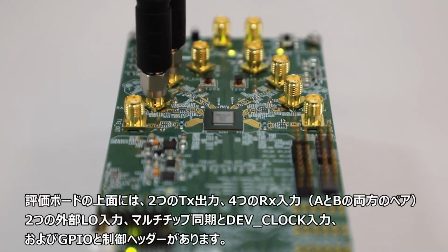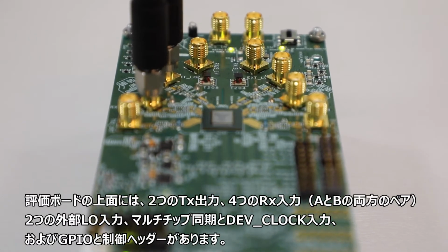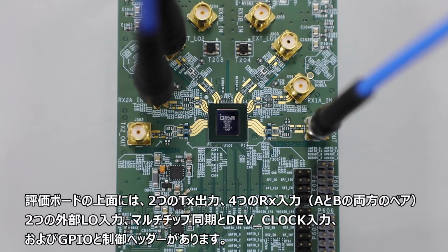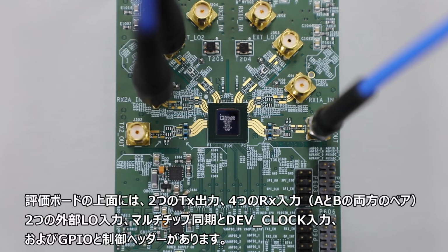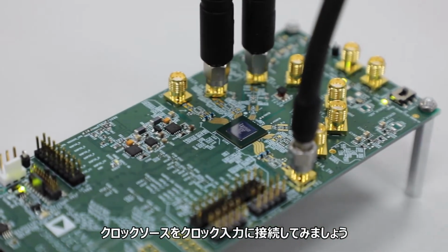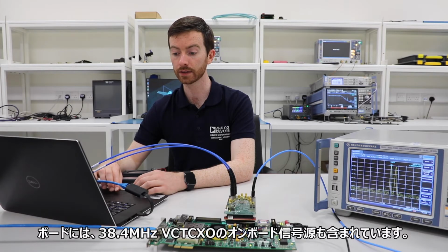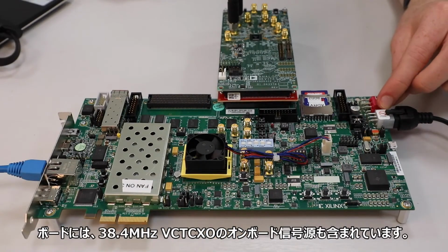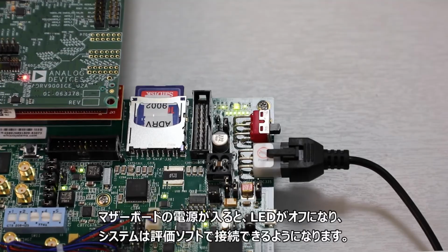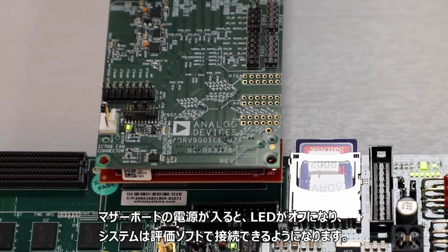The top side of the evaluation board exposes two TX outputs, four RX inputs, both A and B pairs, two external LO inputs, multi-chip synchronization and dev clock inputs, and GPIO and control headers. Let's connect a clock source to the clock input and continue. The board also contains an onboard signal source of 38.4 MHz VCTCXO. Turn on the Zynq motherboard and we'll see the LED sequence. When the motherboard powers up, the LED turns off and the system is ready for connection via the evaluation software.